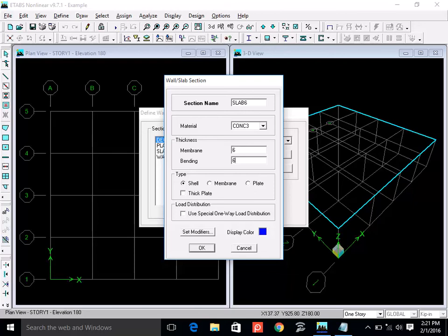We model it as a membrane and apply the live load and dead loads on the slab, which is a membrane. So what ETABS will do, ETABS will distribute it according to tributary areas. You remember those triangles and trapezoids? So it will calculate those areas and multiply the intensity of loading with that area and transfer it to the beams, and then beams transfer it to the columns.